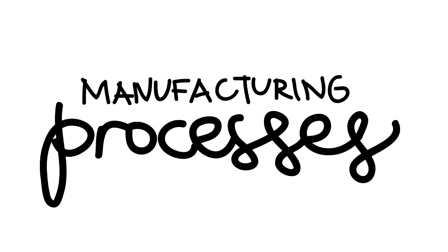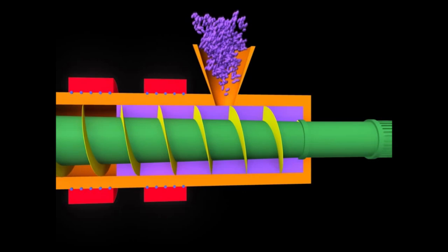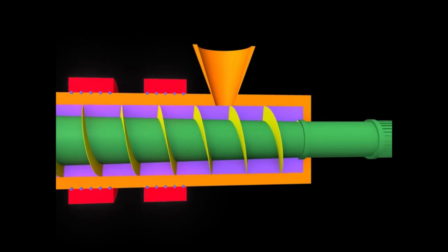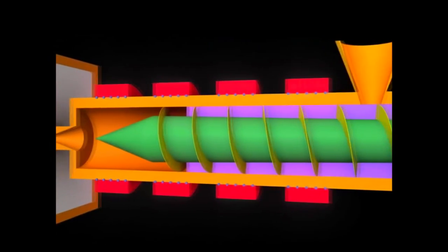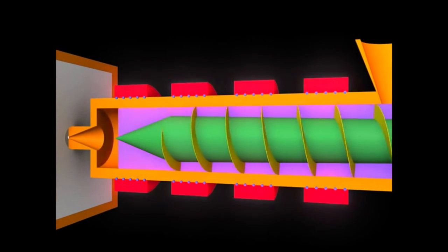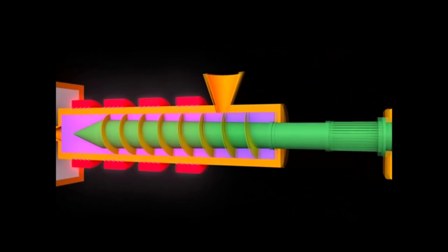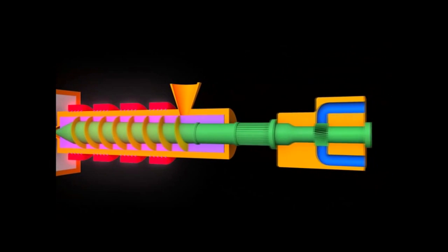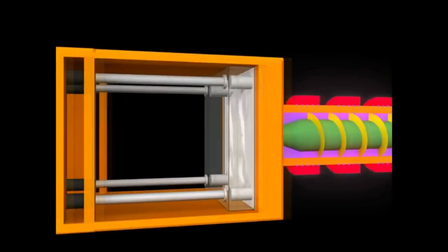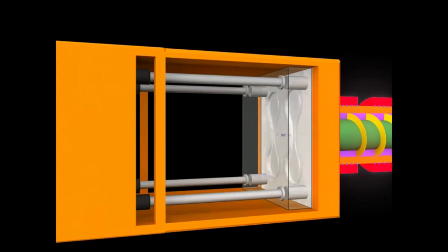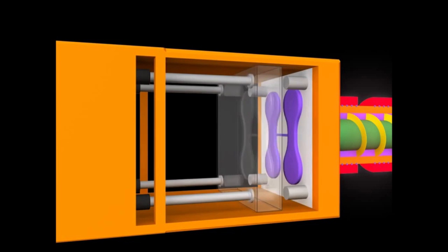Manufacturing processes. Creating the plastic moldings. Plastic parts of the stapler are made by injection molding, in which a liquefied plastic is injected to a die. The liquid flows into the open void and then cooled. As the die cools, the plastic solidifies and takes the shape of the die. The die is opened and the part is removed.